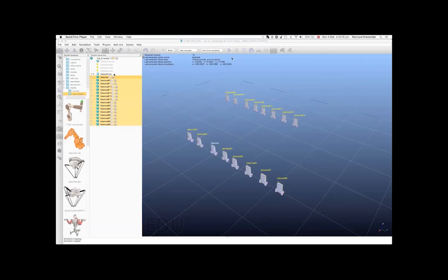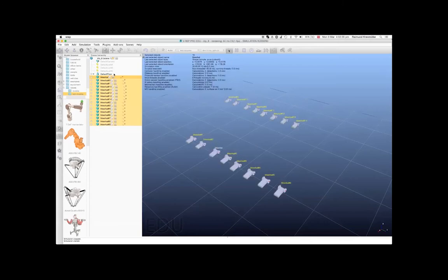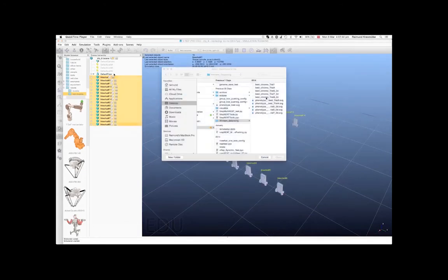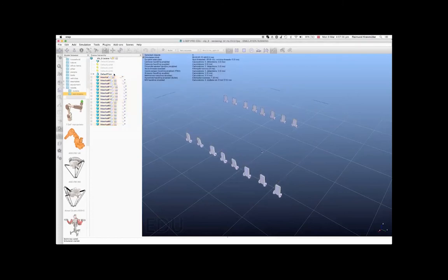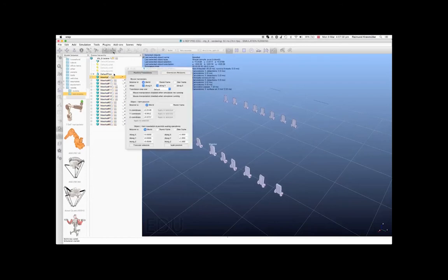Basically, what follows are 4 examples that we actually did during the workshop. We had to use the cooking show principle of preparing a lot of stuff, otherwise in 2 days this would have been impossible. Here you have a bunch of robots that without any control just do random stuff, because it's a physically accurate simulation. They bump into each other, there is friction, there is gravity, and so on. After a few generations of training, we obtain a controller, and in this case the fitness function was designed in such a way that the robots understand how to balance, how to not fall on their face, using their 2 independently controlled motors.